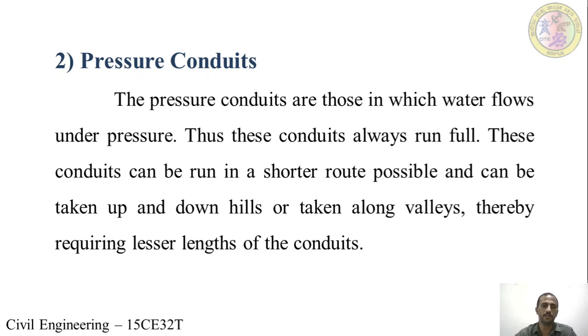Next one is pressure conduits. In pressure conduits, water flows under pressure. The conduits are closed ones, and these pipes always run full. One of the advantages of pressure conduits over gravity conduits is that we can run the pipeline in a shorter line between intake and the treatment plant.